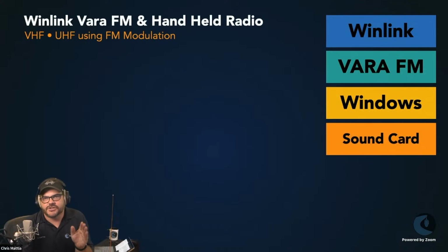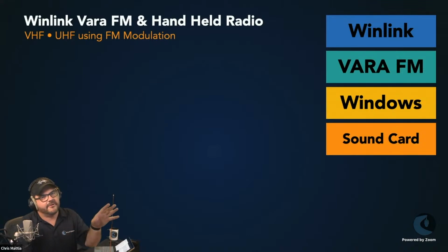The next piece you're going to need is a sound card. Now, a lot of people start to think that, hey, I've got a TNC or a terminal node controller that's either built into my radio. For instance, the Kenwood D74 and D75 have a built-in TNC right in that HT. The problem is that Vara uses a sound card interface to do all of its modulation, demodulation, and be able to send all of the traffic and receive it. So you are going to need a sound card. And a lot of people say, hey, but I've got a built-in sound card in my computer. Really what you want is an external sound card that you're able to better control and set all the right levels and control with your radio. And we're going to walk through a couple of examples for that.